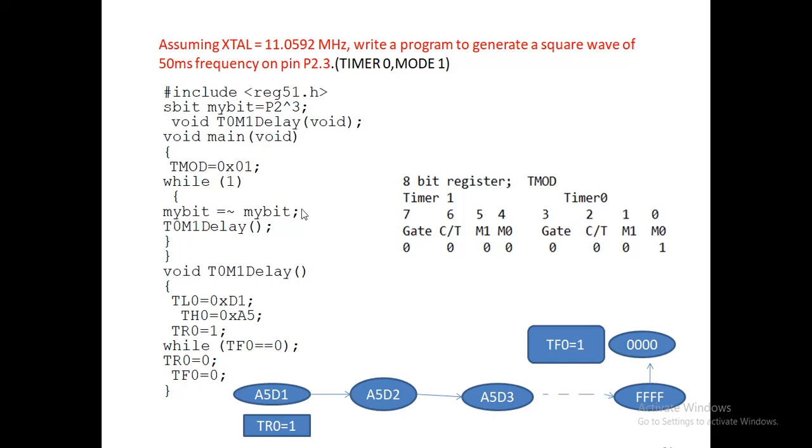Why I am not using this inside the sub function: once you configure this, you need not change anything. Once you start the program, you need not change this TMOD register. It is fixed until you have to change the timer or mode. Until that it is fixed.